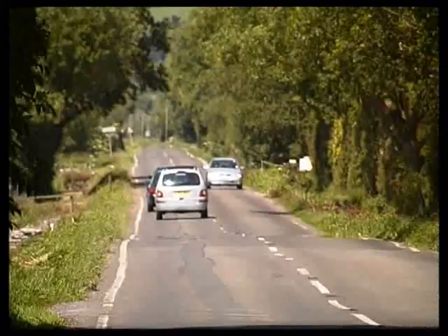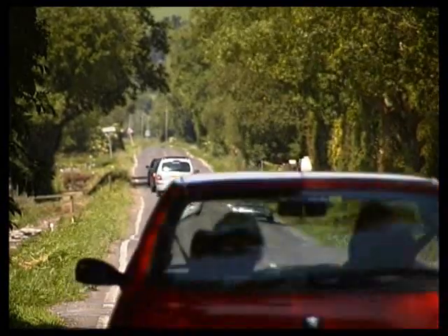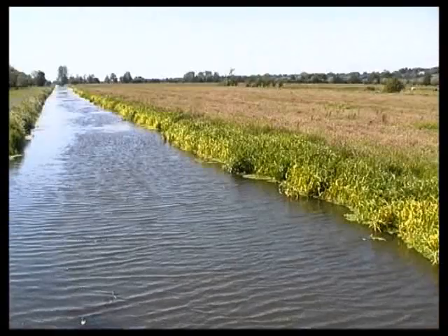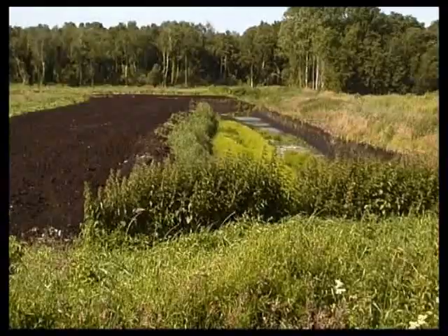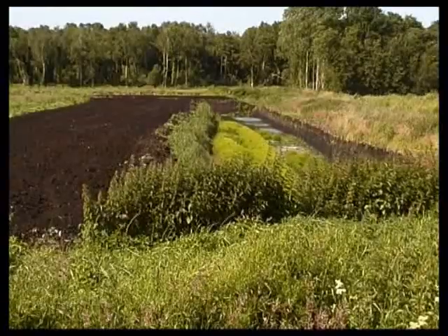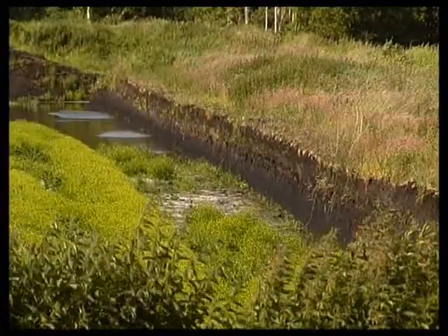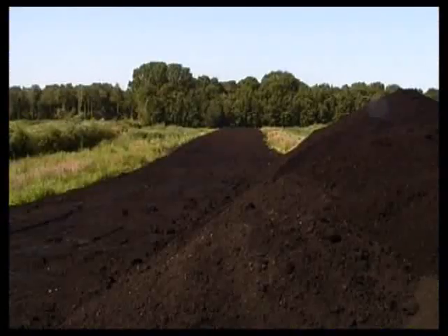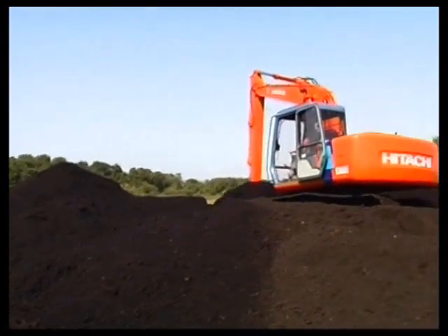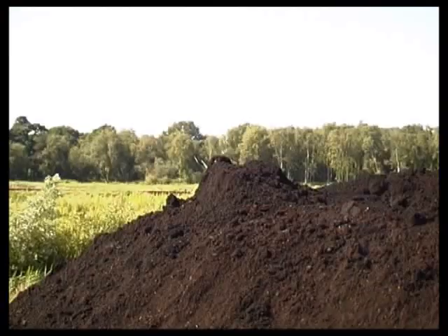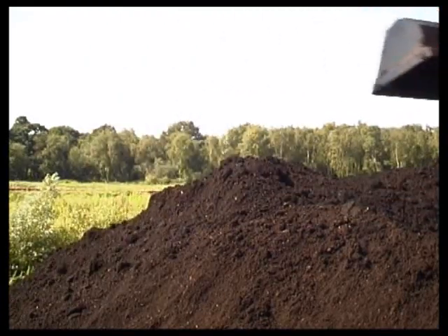This road, crossing the Somerset Levels, has subsided because it's built on peat. Peat is an organic, fibrous material with a high water content and very low bearing capacity. It's black or brown with a distinct odour. Peat shrinks and swells considerably, and its high compressibility leads to high settlement. It's best avoided as a foundation. Despite ecological concerns, it's much in demand as garden fertiliser.